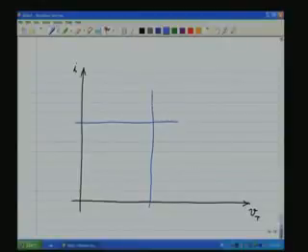So, an ideal photovoltaic cell will fall within this square template that I have drawn here. But there are some non-idealities in the solar cell, that is, it also has a finite shunt resistance, and a series resistance which is also finite, non-zero.